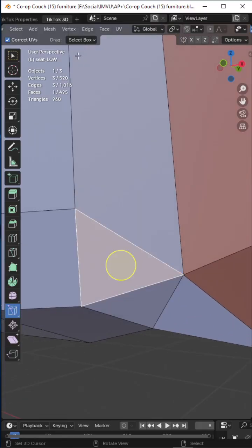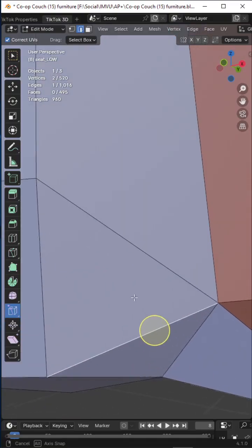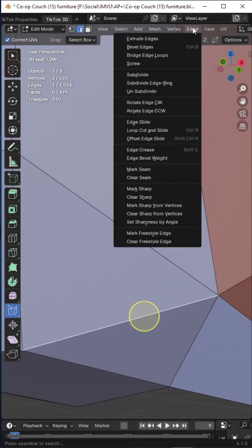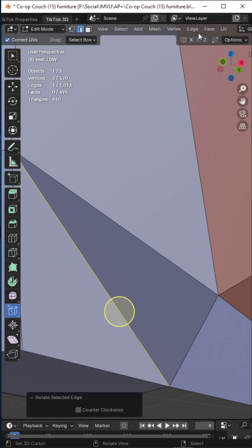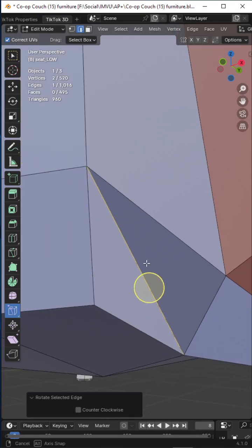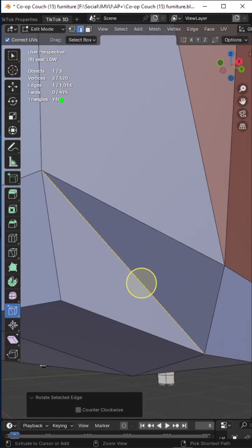Had this not done that, we would select the edge, edge, rotate, and that flips the edge orientation. So this is what's meant about the, so a quad, a polygon, is 4 edges, but the smallest element is a triangle, and the smallest element below that is an edge, and then the smallest element below that is a vertex.